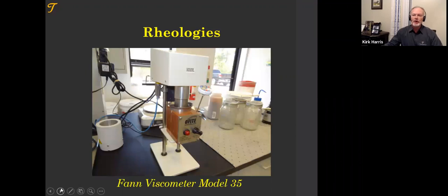It is a good thing to know whether your lab is using heated cups as a regular routine or not. Again, my experience is that many do, but I would say most do not use heated cups. And so when you measure the temperatures of the slurries as directed by API, you'll find that they have cooled down. If you've solubilized polymer and you start cooling it down, it gets more viscous than what it would be at temperature.